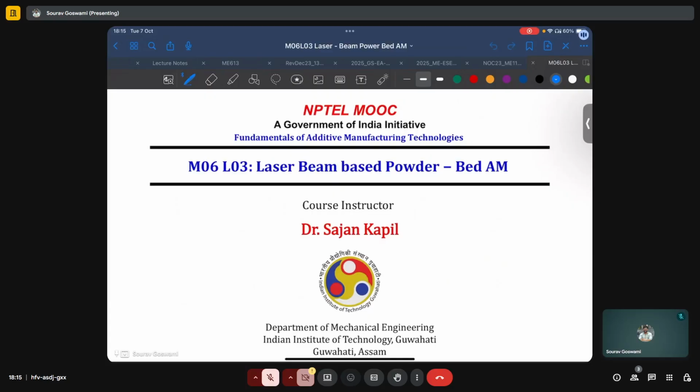We also looked at the ways in which energy addition to the system is simulated, typically by the use of an energy source, which may be of volumetric or surface kind, how they're implemented, how heat losses such as due to convection and radiation are modeled. We also saw how we can just use a single effective heat transfer coefficient to model the effect of both, and what effect nonlinear material properties will have on the solution.